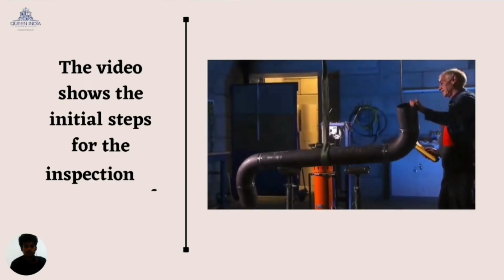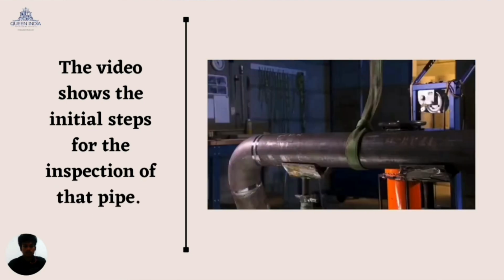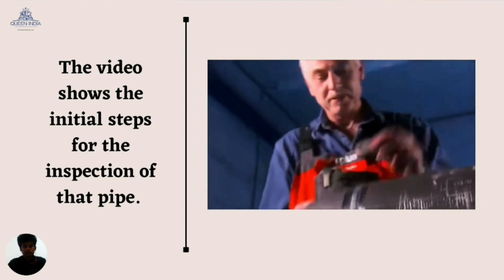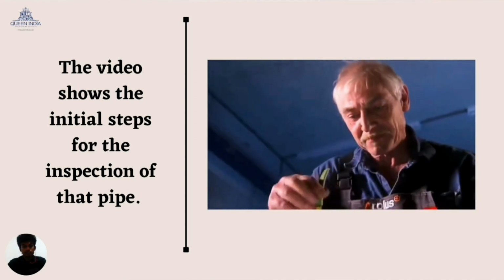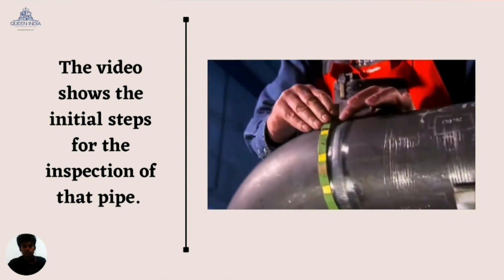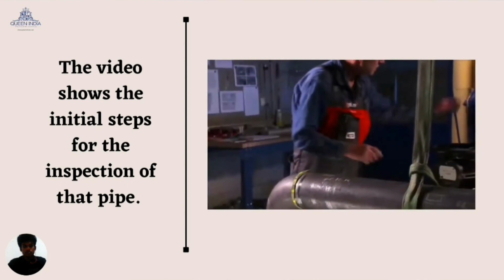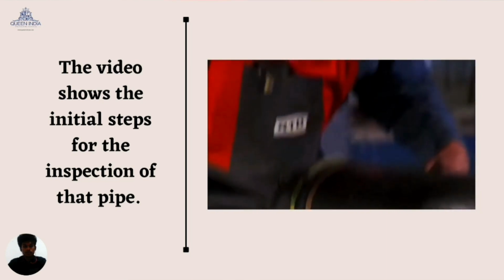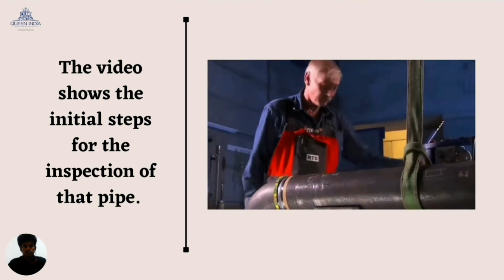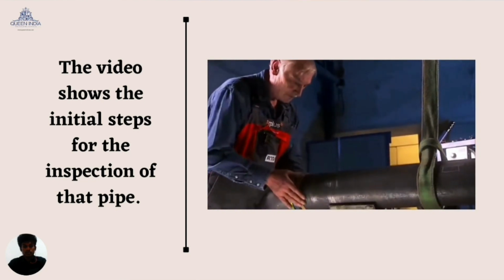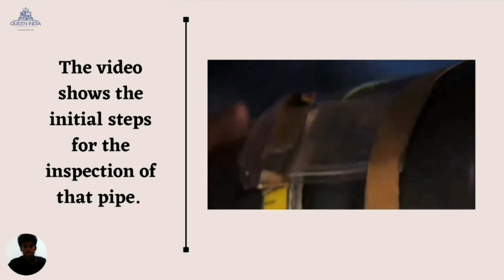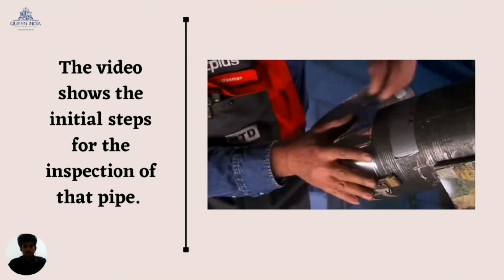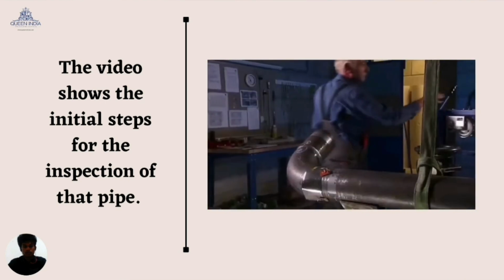Radiography testing utilizes ionizing radiation to achieve an image of an object on several different viewing mediums. This may be gamma rays or, as in this case, X-rays. Here the examiner marks the belt to be inspected with a measuring tape. This will be visible on the X-ray, thus he will know how to determine the exact location of possible irregularities. Then the film is mounted on the object and the X-ray tube is set up carefully.